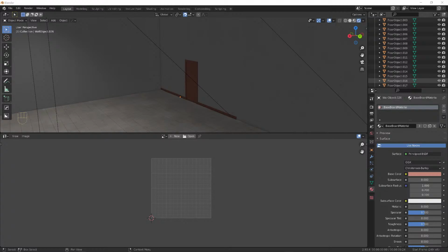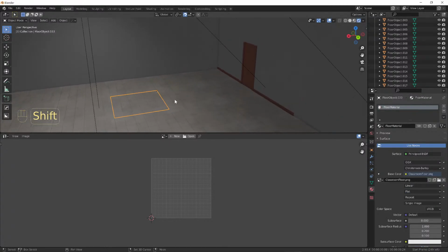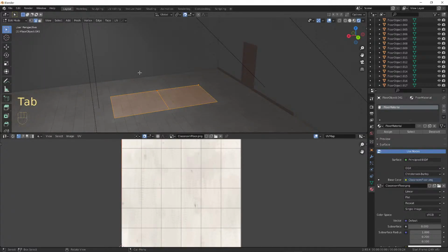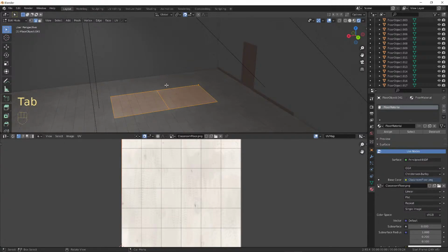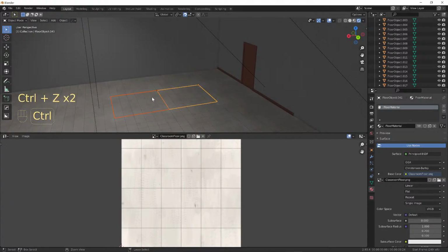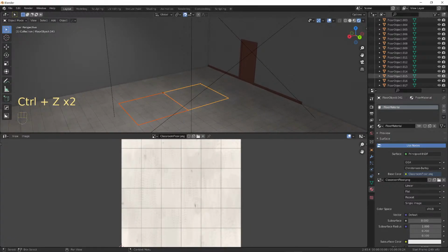Steven, just make sure you're not, because you can select, I'm just seeing your comment now, you can select multiple objects like this in object mode, press Tab to go into edit mode and try to merge. It'll never merge because they're separate objects, they live in separate containers. To merge the geometry, you'll have to select the two objects first, then join them by pressing Ctrl J. Okay, Ctrl J to join. And then they live in the same container, and then you can merge them by distance. I suspect that's the issue that you ran into.